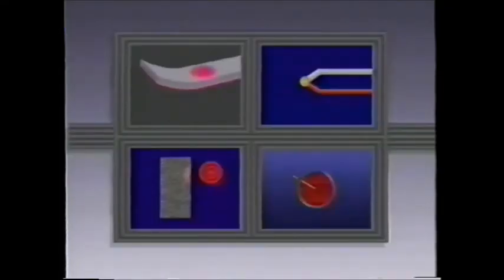Among the advantages of thermal wells is that they allow removal of the sensor while the process is in operation. Their primary disadvantage is increased response time. The thermal conductivity of the walls of a thermal well and the substance inside it, typically air or a liquid, reduce the response time of the sensor. Your workbook contains some additional information on the measurement of temperature in industrial processes, the types of detectors, and thermal wells.